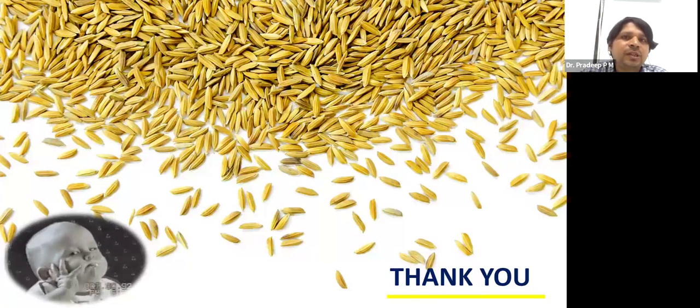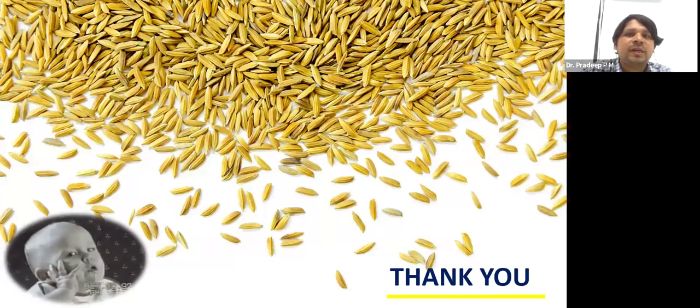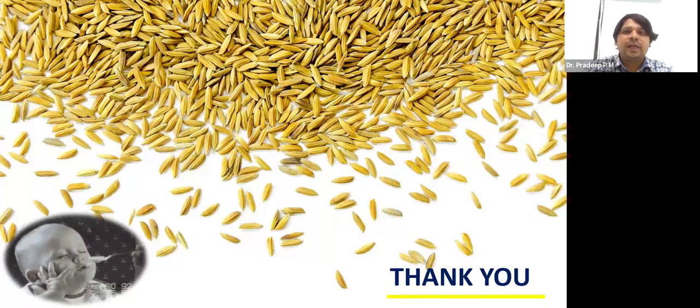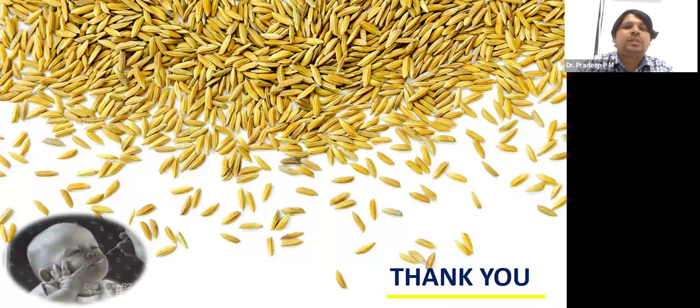So there may be damages to the paddy by microorganisms or it can get infested. So to overcome that, we have to go for drying. That means we had to reduce the moisture of the paddy from 18 to 12%.